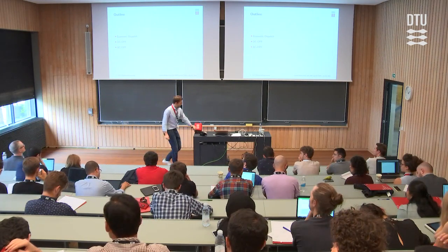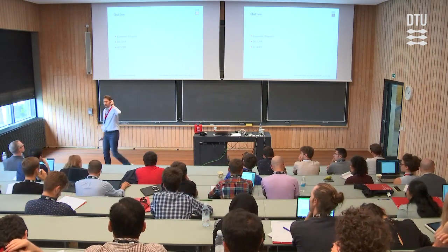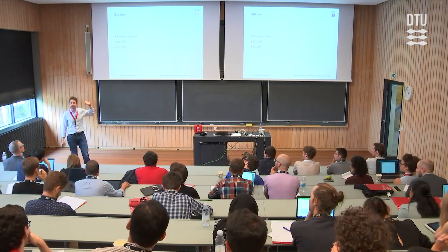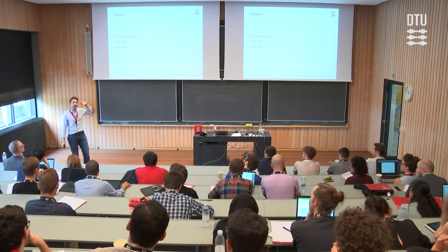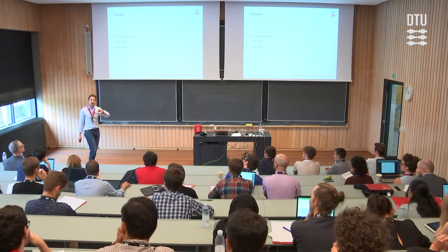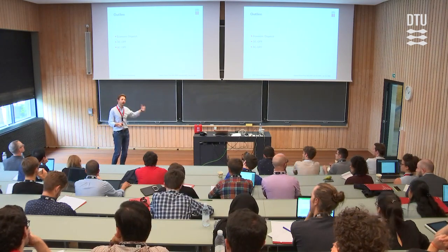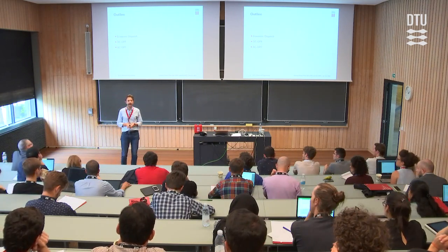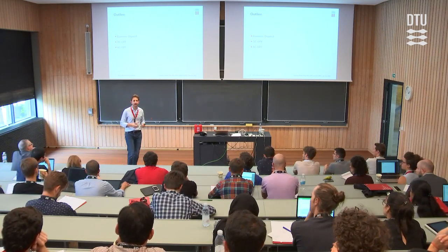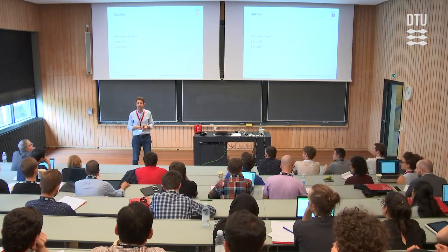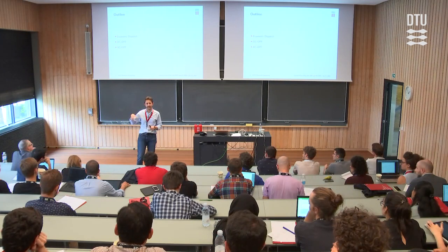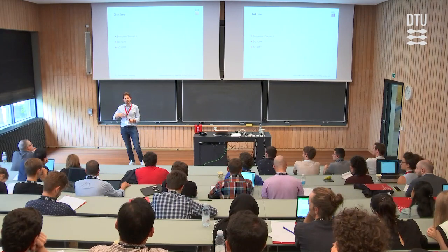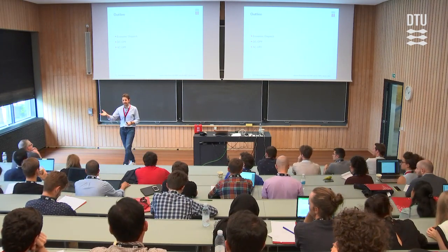So what I really want to make very clear here is that when we talk about DC-OPF and AC-OPF, this has nothing to do with AC and DC current. Okay. In the past, we had no HVDC lines, no direct current flows. So people thought, okay, let me approximate the nonlinear equations of the alternating current with a linearized form, and I call that DC. But DC and AC-OPF are just relics of a previous time, and we still use them. They are still valid, but they have nothing to do with alternating current and direct current.